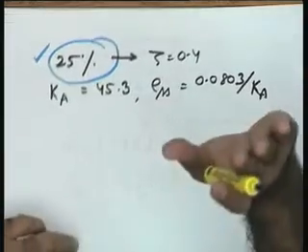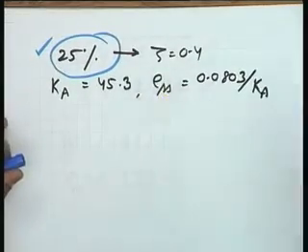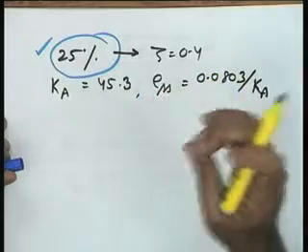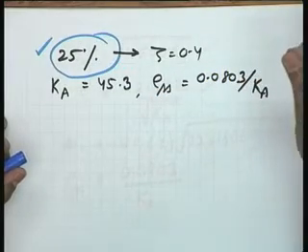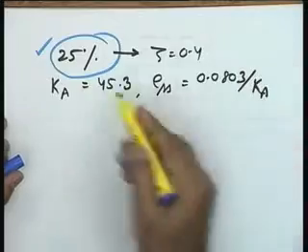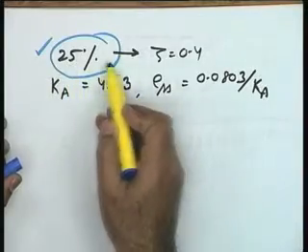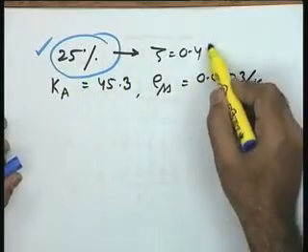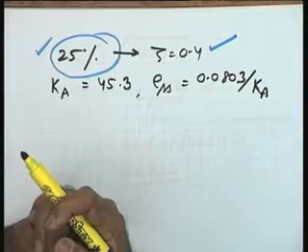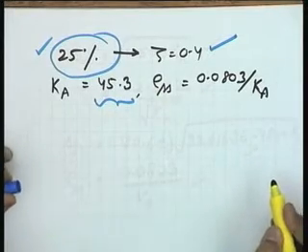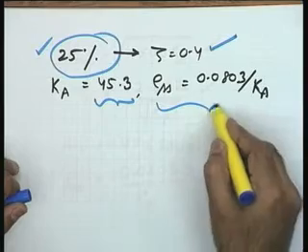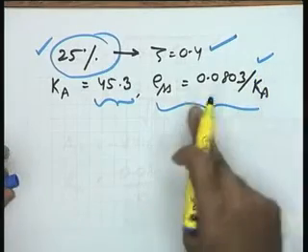Now you see, though the settling time will be larger, still you are allowing the lower values of zeta because you want to get better steady state accuracy. You want to get better steady state accuracy, please. So in that particular case, you have allowed 25% over here, and this corresponds to zeta equal to 0.5. And this zeta equal to 0.5 is 45.3 in this particular case, and the steady state error correspondingly is